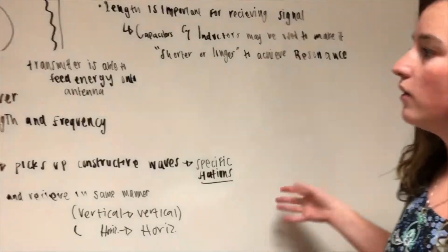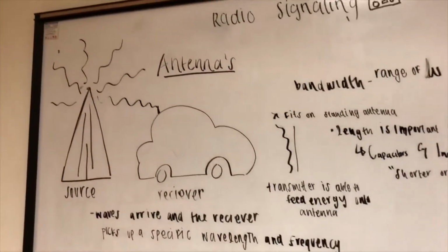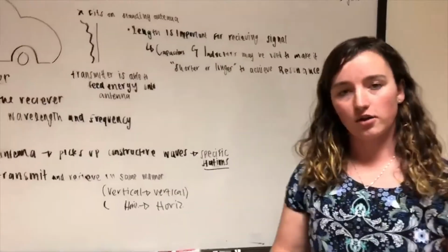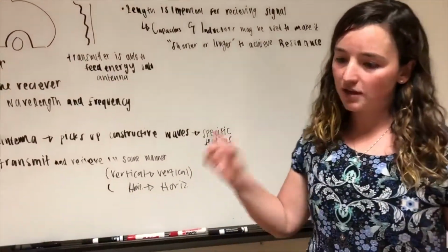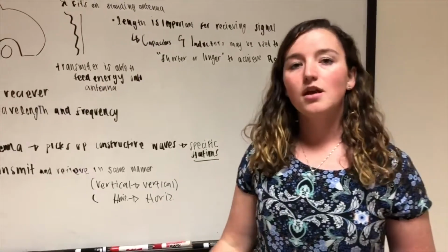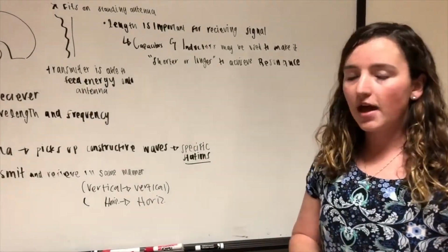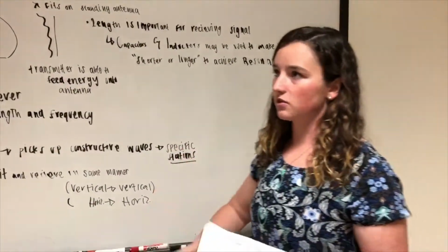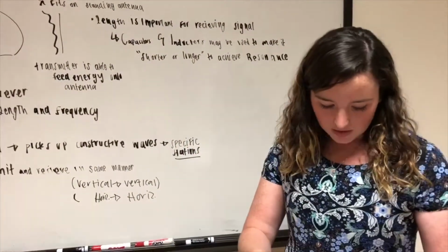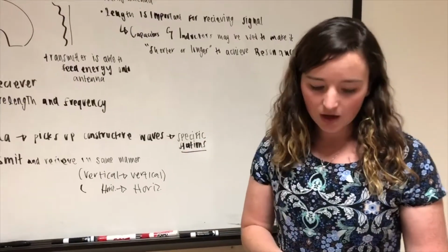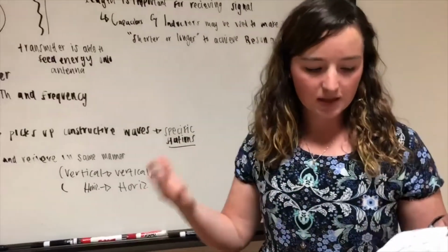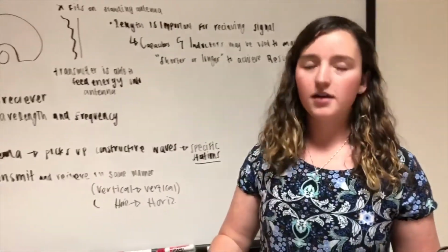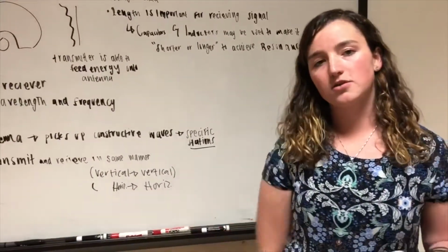So your radio has a little thing called an oscillator that's going to send out a frequency of 745 kilohertz. And so 1200 minus 745 kilohertz is 455 kilohertz. And that is the resonance frequency. So once you filter that resonance frequency through the bandwidth filter, then it's going to hit a demodulator, and we'll explain that in depth a little bit later. And then it's going to go through an amplifier, and eventually you'll hear it through the speakers on your radio.